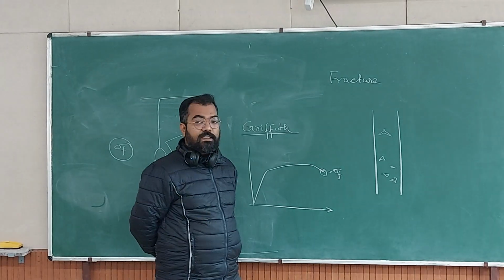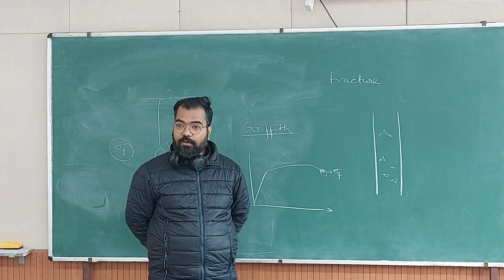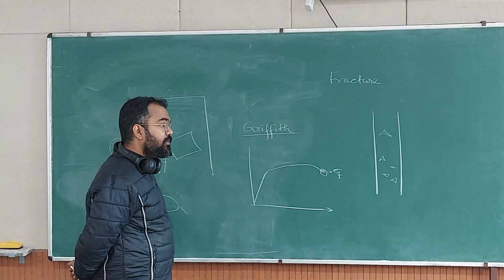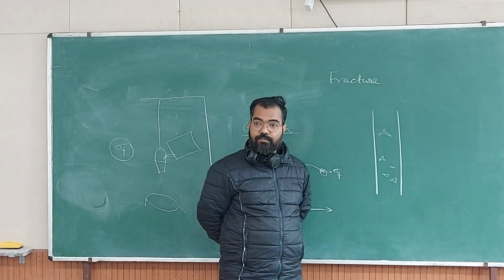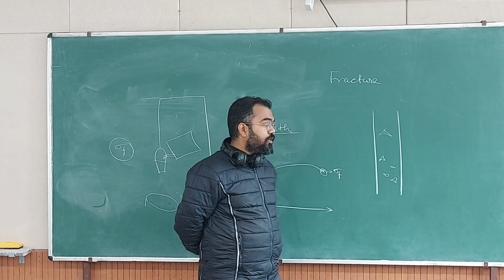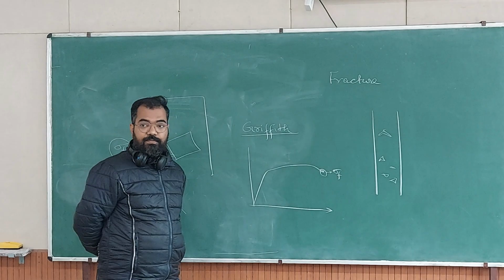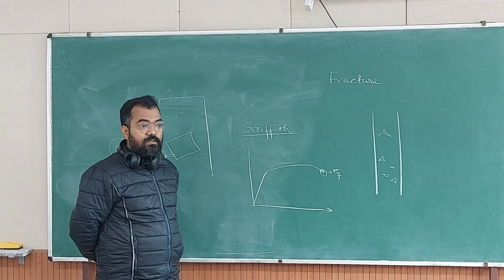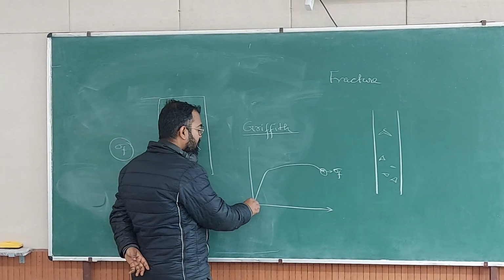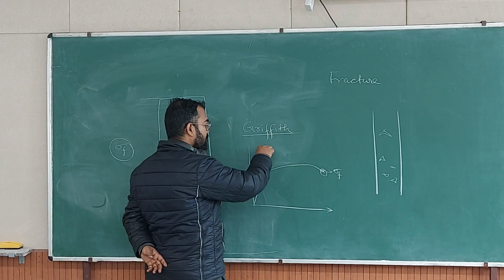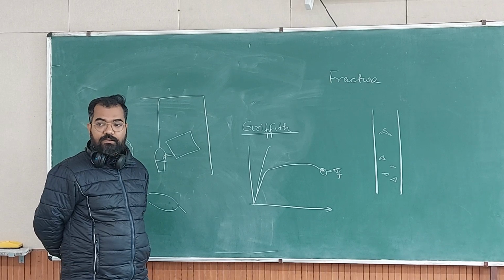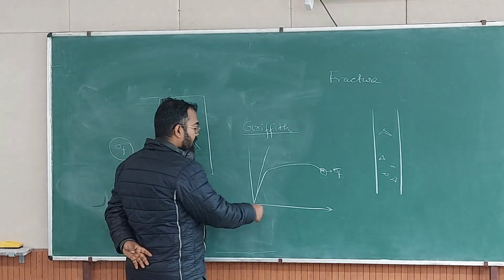So these will act as stress raisers, right? They are loaded. Initially they are in continuum, so whatever load is there is transferred to the matrix as well as the inclusions. If you draw the stress strain diagram of just graphite or carbide and iron, they will have a huge difference. Graphite will be very brittle, and the elastic modulus might also be different. It will go something like this, a little bit of plasticity if at all, and then it will fail.